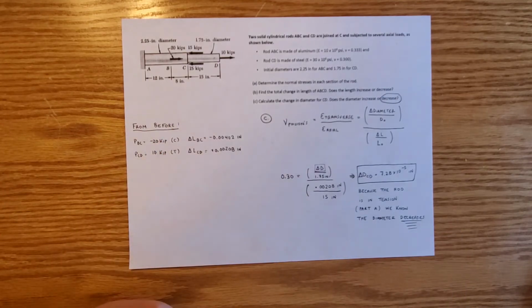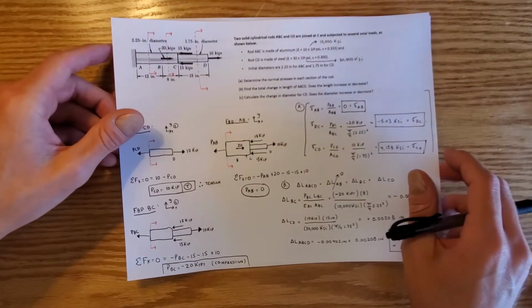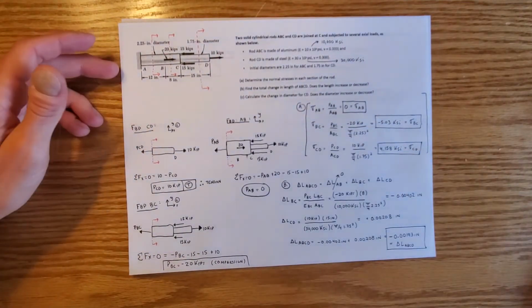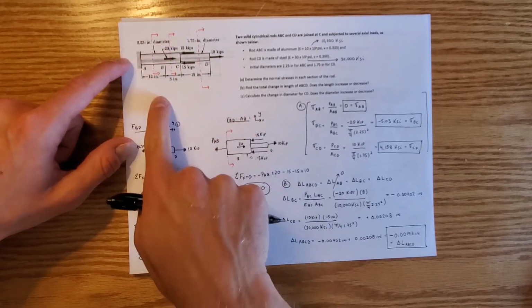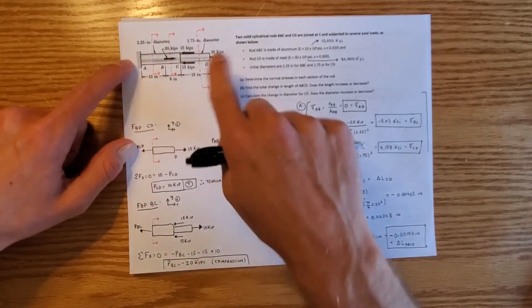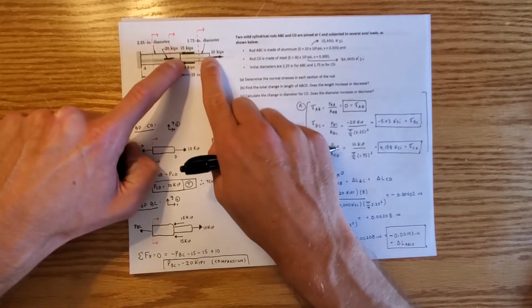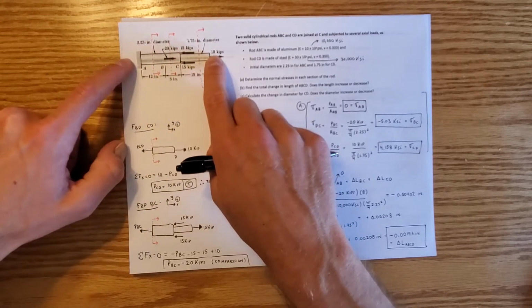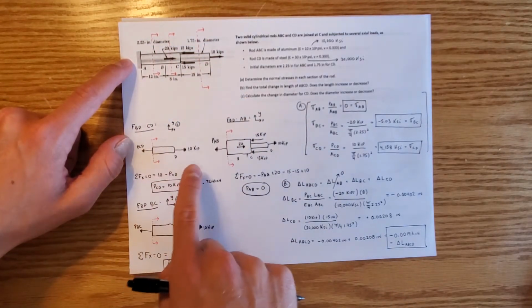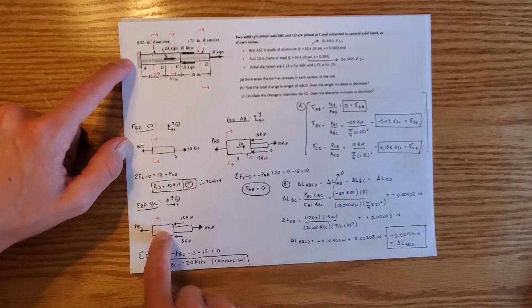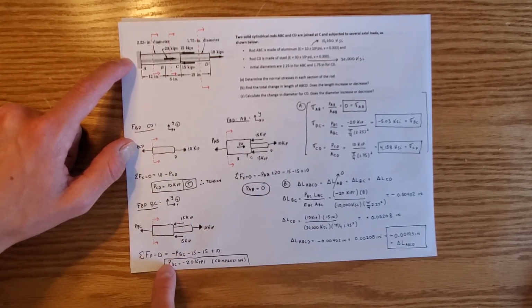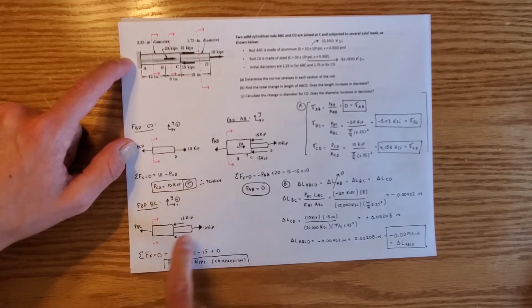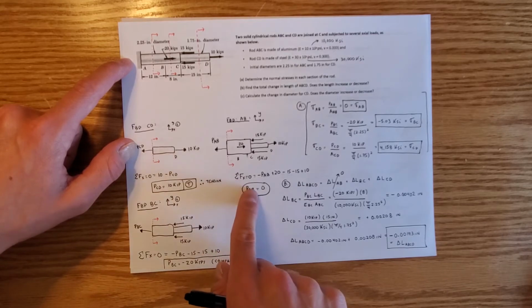Just to review, I'll bring in the other sheet of paper. The solution methodology that we follow is to make a cut in each section of the rod. Here we had to make 3 cuts in between each of the letters, or in between every time that there's a change in forces being experienced. So we drew free body diagrams for section AB, BC, and CD. We did sums of the forces to put the internal normal force of each section in context of the other applied forces. So we found that for everything.